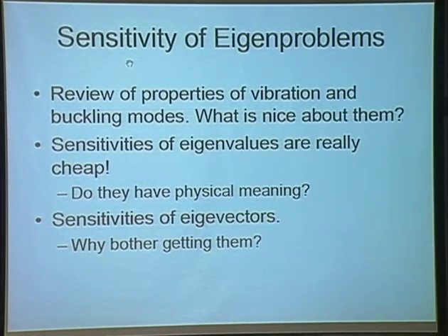Let me give you a clue to one very important application. Car designers put in a lot of effort to make sure that the important vibration modes of a car have a desired shape. In order to avoid resonance? No, avoiding resonance depends on the frequency, not on the mode shape. What's the difference on the cars? The impact? No, let's just talk about vibration.